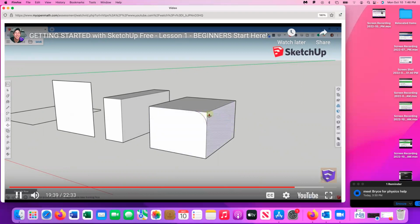Well, now I could activate the push-pull tool, and remember how before we used this to add material. If I single click on this face and move my mouse to the back, you can see this actually removes material. One thing to note is that I'm getting this message that says the offset is limited. I can't push pull this back any further because it has reached the end of the shape that's back here.